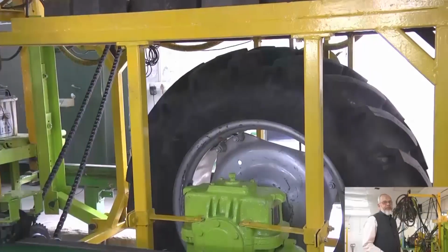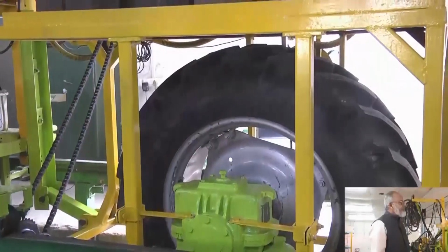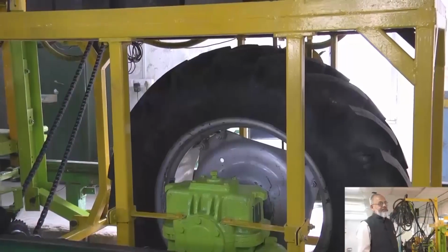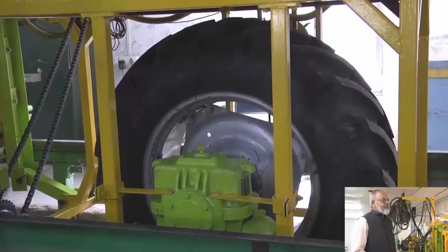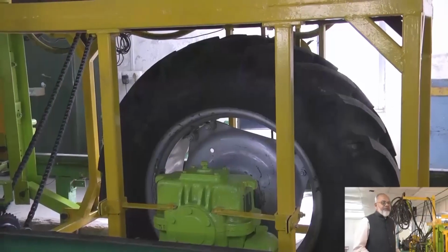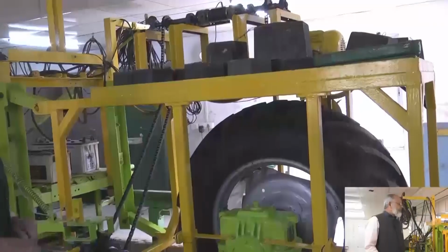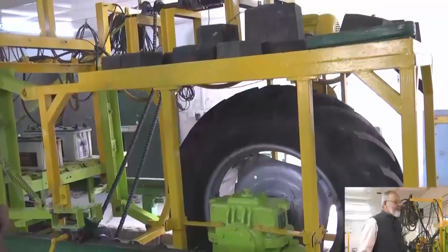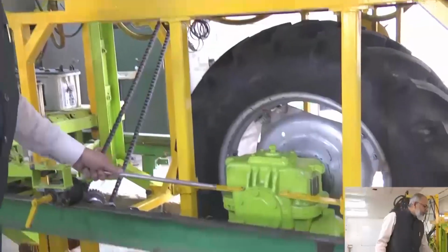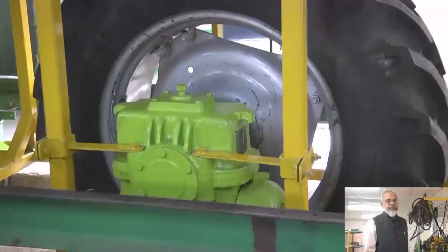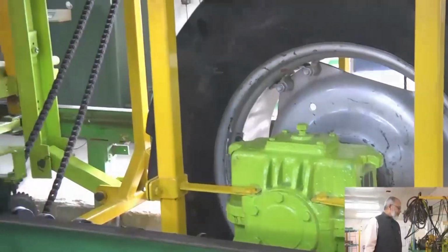Then the power has to be supplied, that is the important thing. Power has to be supplied to the axle of the wheel. We have taken it from an electric motor, a 3-phase AC motor. The 1450 RPM has to be converted into an RPM corresponding to 2.5 or 3.5 kilometer per hour. So, we have made a transmission arrangement with gears, chain and sprockets, which gives a positive drive, so there is absolutely no slip, and then there is a gearbox. Finally, we want more torque and low speed, which is possible with the help of this gearbox and the chain and sprocket drive.